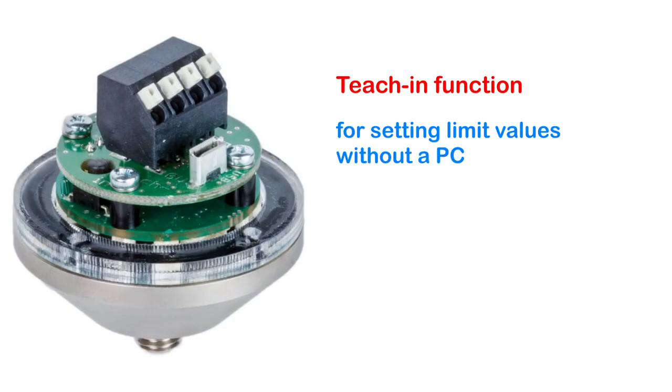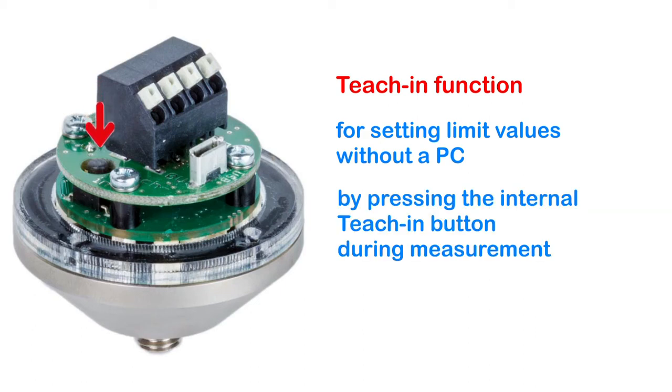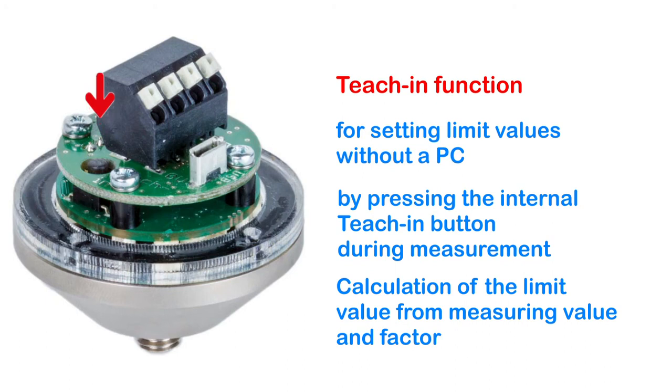A basic setup is also possible without PC, by means of the teach-in function. Inside the case is a push button, which can be pressed through a hole in the lid, after removing a cover screw. After pressing the button, the device will measure vibration for some seconds, and then calculate the limit value, by multiplying the measured amplitude, with a user-selectable factor. The teach-in function also operates in FFT mode.